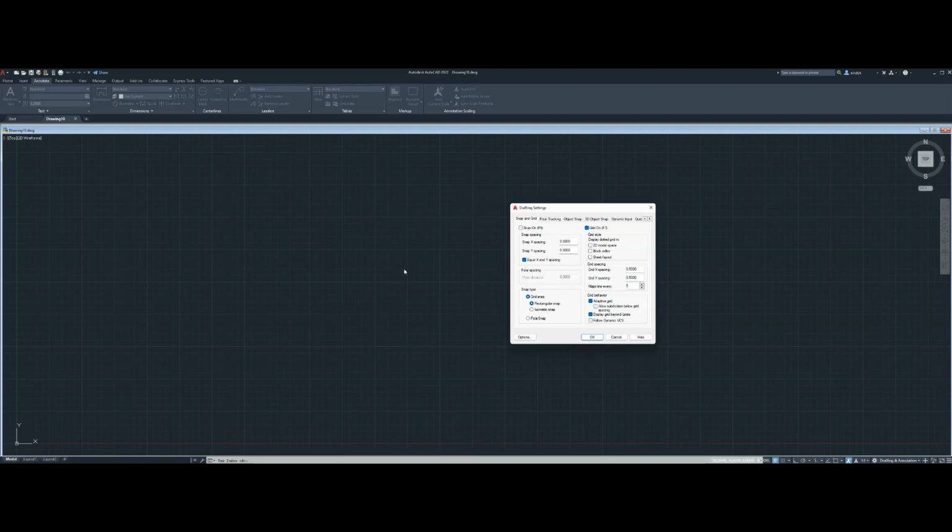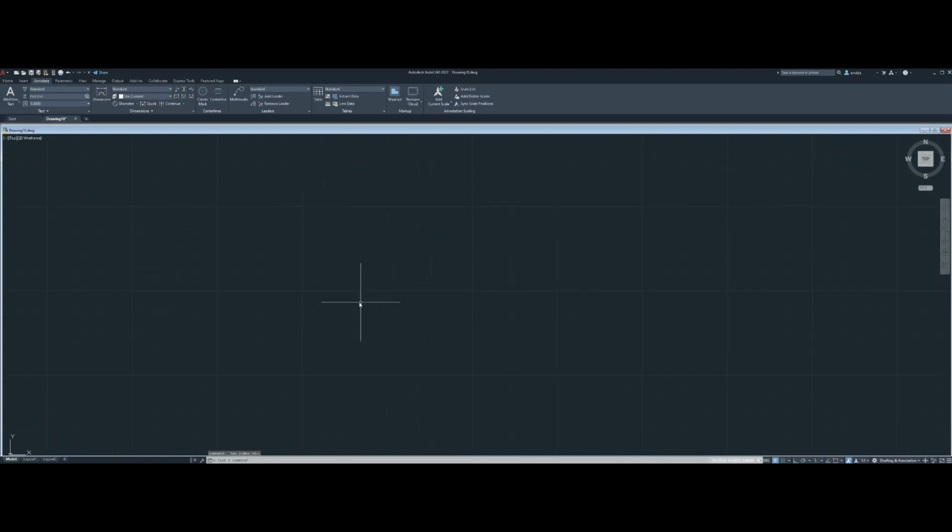By default, the grid line has minor lines every half inch and major lines every 2.5 inches. I will change them to a 1/4 inch and major grid lines every inch. This gives you an idea of scale whenever you draw. You may want to change them differently, but for this purpose, I change them so I basically see 1 inch squares.